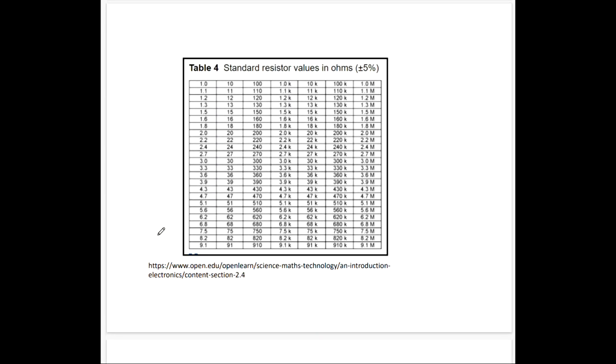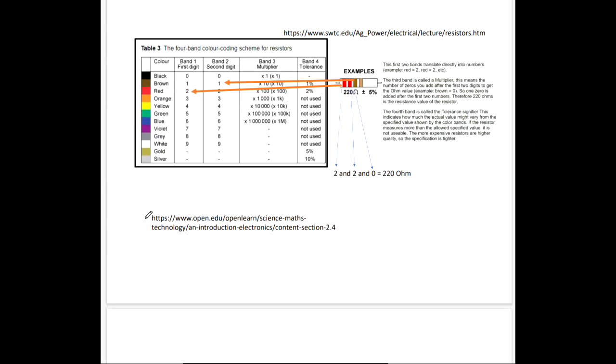And the resistance you want comes in standard values. As a designer, you want certain resistances in your circuit to achieve certain functions. And you can pick from these standard values, like a 1 ohm resistor, a 100 ohm resistor, 24K. 47K shows up quite a bit in audio. You have your mega ohm. We just created a 1 mega ohm resistor downstairs. I think we created, did we create a 6 mega ohm resistor? They come in standard values.